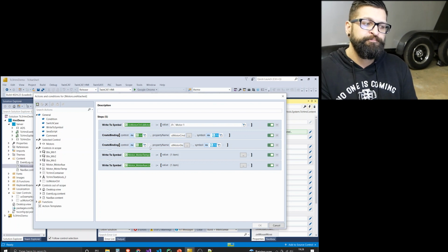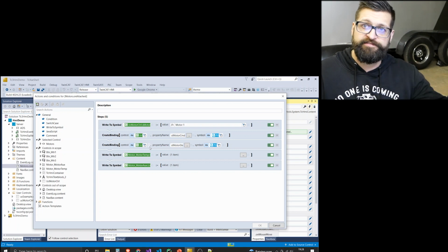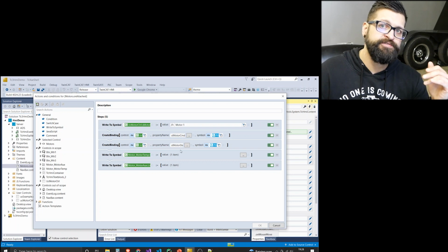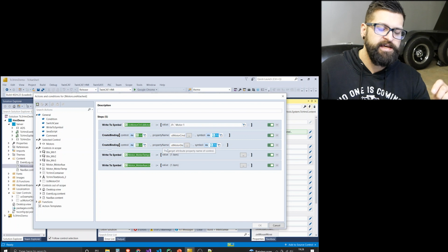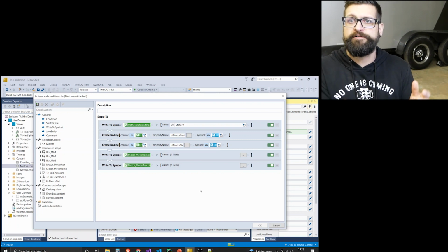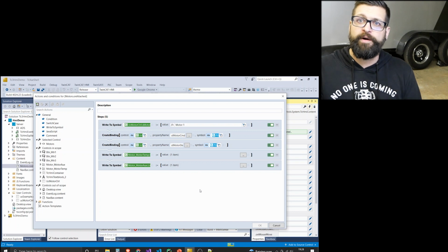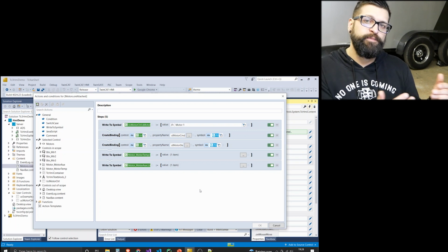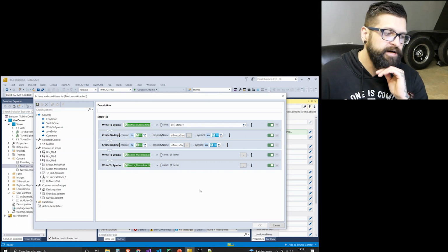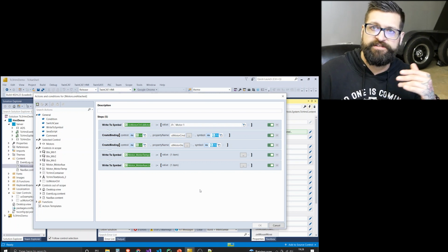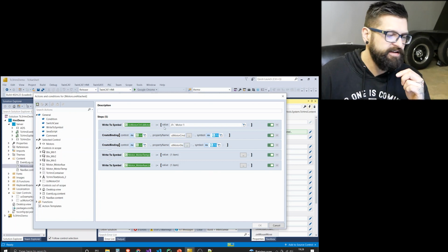You could have it so you remember. There are internal variables and server variables that only live on the server that you can use for your HMI logic, and you could set something up that says, remember the last data set they were on before they navigated away from the motor page, so that when they went back to it, it showed them the same motor they were on. You can do that. You can do whatever you want. But I've chosen to do it via the onAttached event, so that every time it just shows the motor 1 data sets.